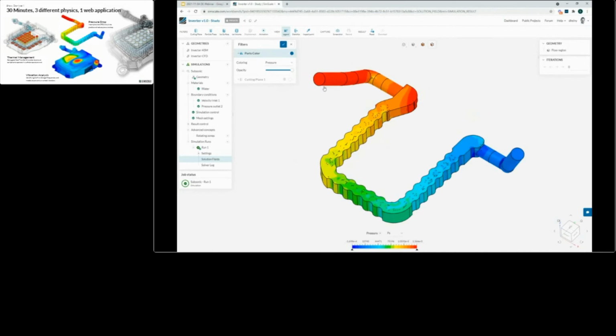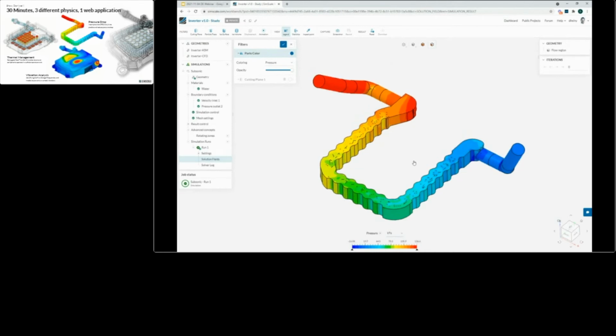So I'm having, let's change this to kilopascals. I'm having high pressure over here, low pressure over here. I defined this to be 0. We can also inspect the point. So pressure over here I defined to 0 gauge pressure, right? And then I have 130 kilopascals over here, and that's where I already can sort of gauge. I see the pressure drop across this channel.